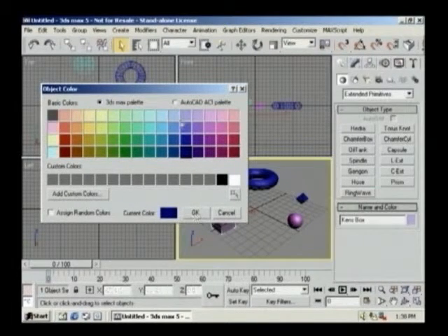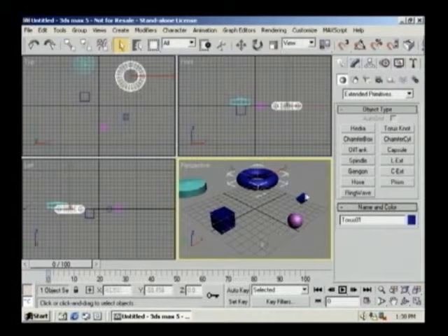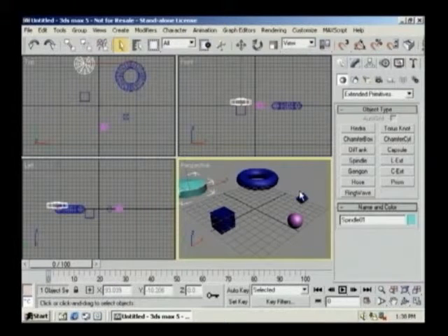As I said earlier, the default tool that is active when 3ds Max first opens is the Select tool. You obviously use this tool to select objects and multiple objects. Now the key thing about this tool is that no transformation is performed while you use this tool to select objects. To transform objects, you need to use one of the Select and Transformation tools.